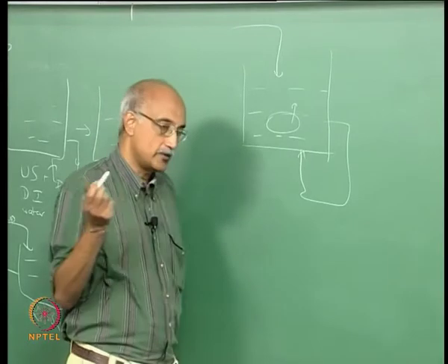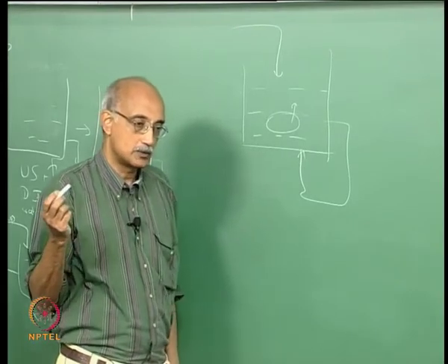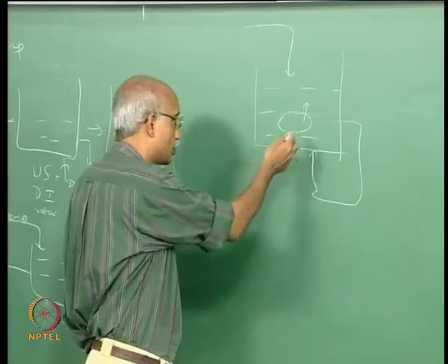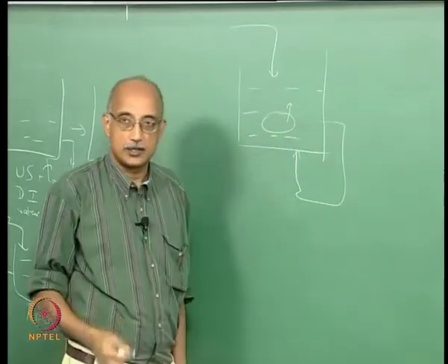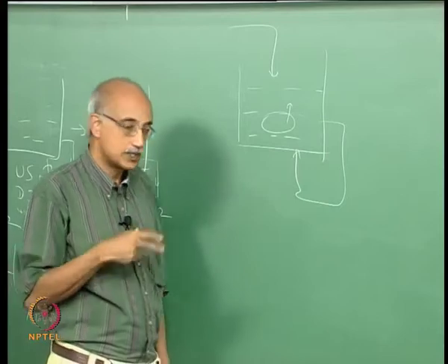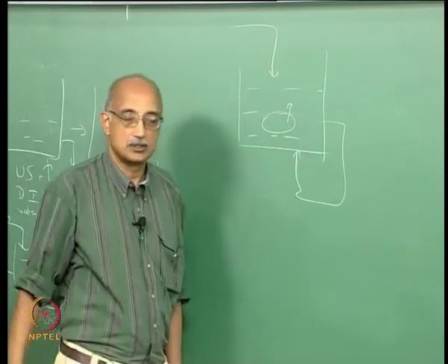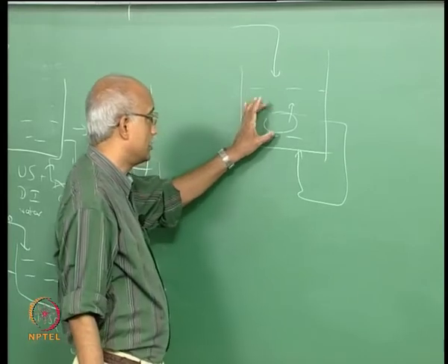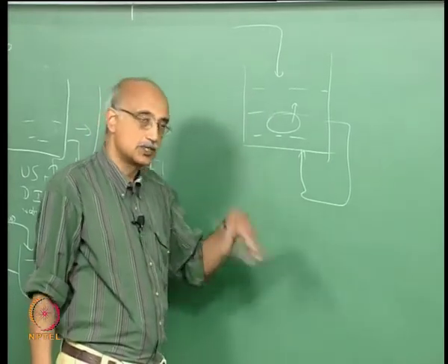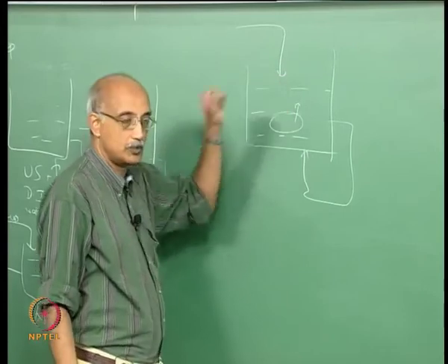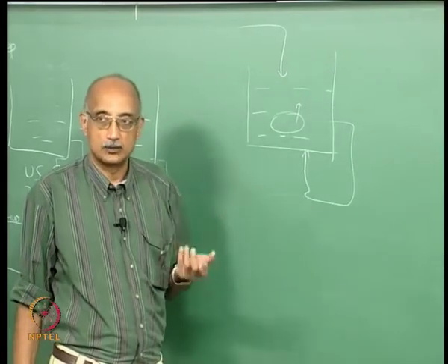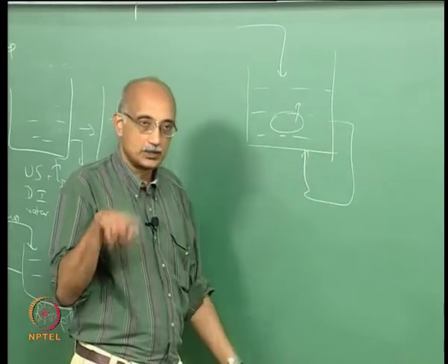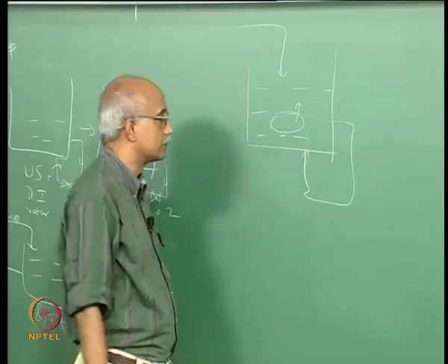And just like we were able to optimize the operation of a clean room by looking at sources inside versus sources outside and the rate of recycle, similarly we can do an optimization algorithm here by looking at how many particles are being contributed by the wafer versus how many particles are being contributed by the cleaning medium or liquid itself, and by again suitably changing the rate of the recycle.